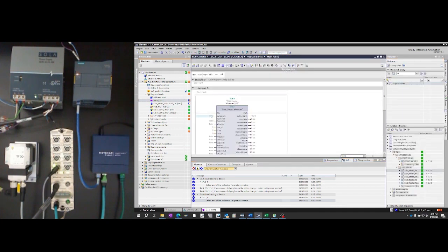For the ref input, you'll need to add the second available input byte. Since we started at 3, that will be input byte 4. And for by device available, that'll be input byte 5. Remember that input byte 3 is reserved and input byte 6 is not used. That's just there and allocated due to byte boundaries in TIA Portal.